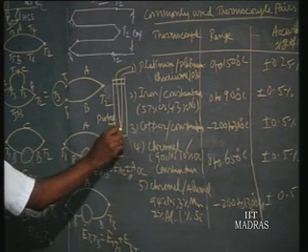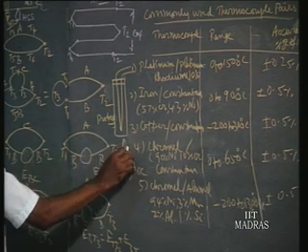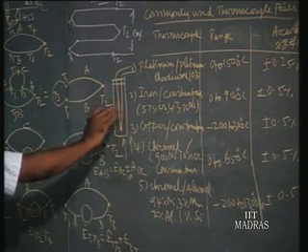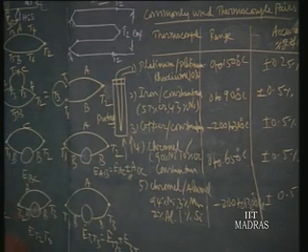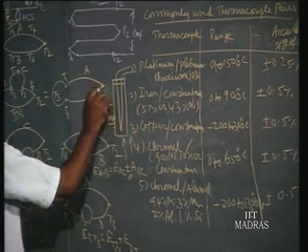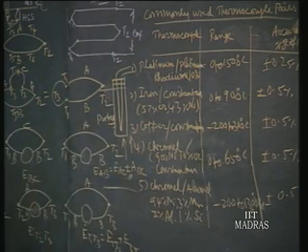It is to protect the junction, otherwise you will find some flue gas flowing. If you want to find the flue gas temperature, some dust may fall on the wire and contaminate it, and it may change the calibration curve. So for that, it is just inserted in the pipeline, and there is a protection tube.